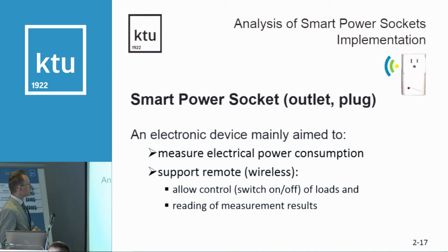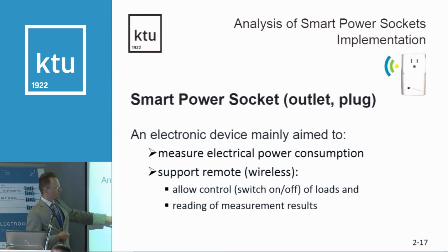So these electronic devices are mainly aimed to conduct several tasks: to measure electrical power consumption at every point of electrical power consumption, and support remote, mainly wireless, though it could be a power line communication, control of loads on and off, and of course reading of measurement results.